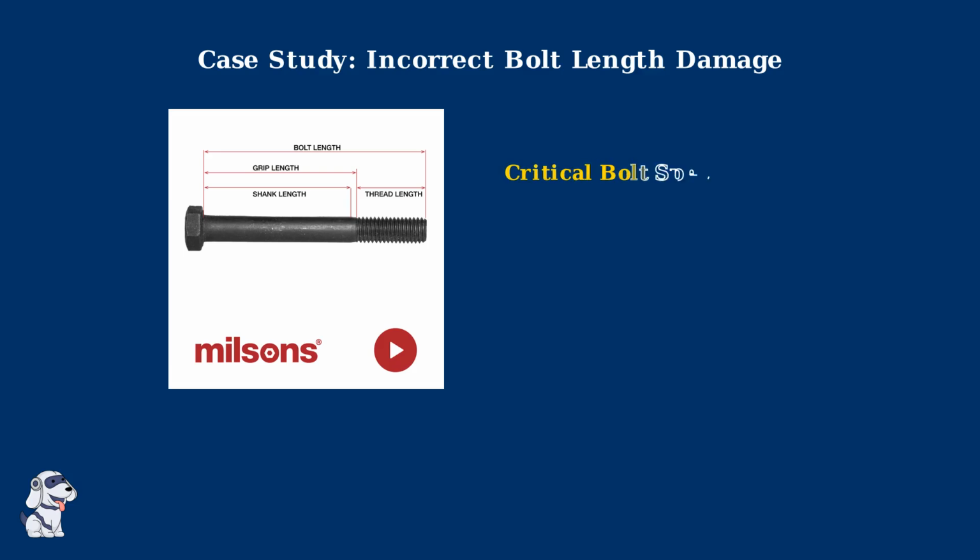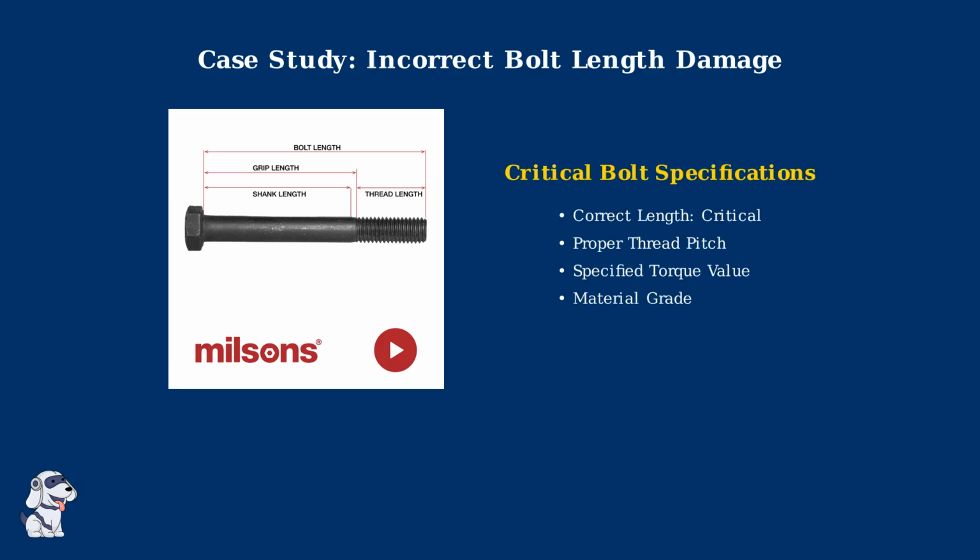In this case study, we examine a critical installation error that can cause severe damage to the TEHCM and valve body, using incorrect bolt lengths during assembly. Proper bolt specifications are absolutely critical for TEHCM installation. Each bolt must meet exact length, thread pitch, torque, and material requirements to ensure safe and reliable operation.